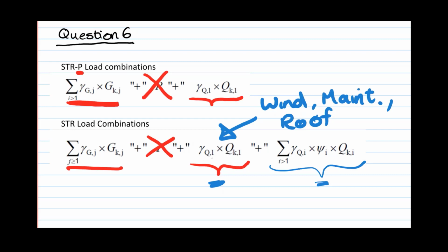So we're going to try all the wind as leading, all the maintenance roof load as leading, and services, and then the roof crawl beam. We're going to try all these different loads and see what happens. When one load is leading, that which is not correlated, not linked to it, for instance maintenance and a crawl beam at the middle of the roof, they act independently.